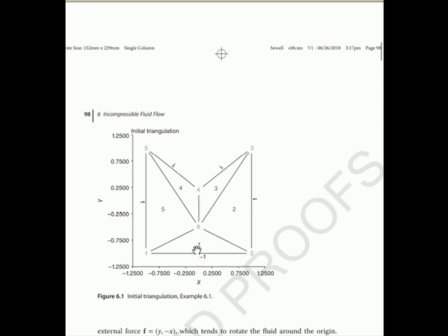where we're going to have free flow conditions, which means V is zero here, the perpendicular velocity is zero, and U sub y is zero. U is not necessarily zero here, it is on the other parts, but it can flow, but U sub y is zero at the boundary. So on 4 pieces of the boundary, U and V are both zero, and that's easy. Those are just fixed boundaries. Our unknowns are both zero. On the bottom is more complicated.